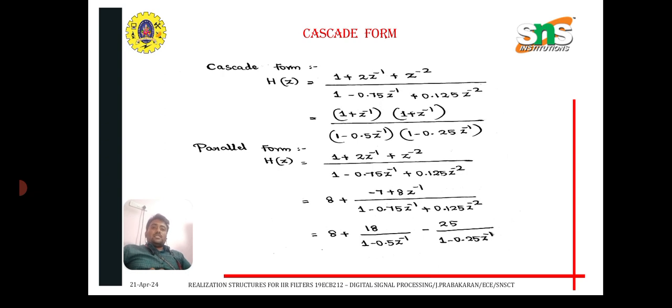Okay, this is an example of cascade form. That is, H of z equal to (1 plus 2 z inverse plus z power minus 2) divided by (1 minus 0.75 z inverse plus 0.125 z power minus 2). The second order equation has to be converted to first order factors, that is, (1 plus z inverse) into (1 plus z inverse) divided by (1 minus 0.5 z inverse) into (1 minus 0.25 z inverse), which is equal to H of z.